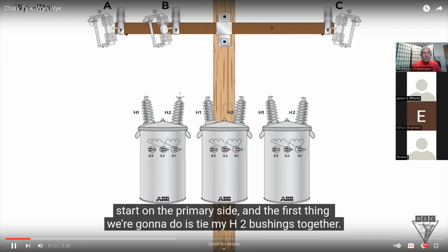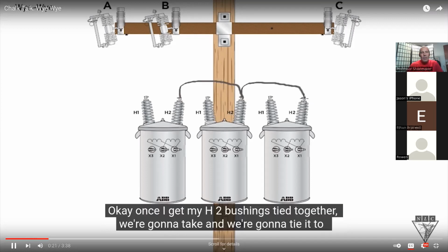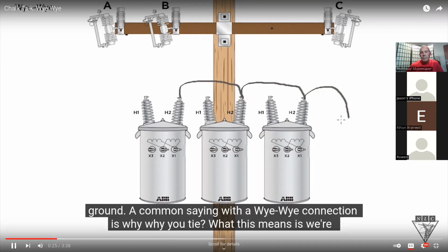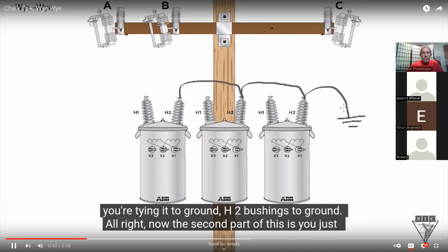I want to tie my H2 bushings together. Once I get my H2 bushings tied together, we're going to tie it to ground. A common saying with a YY connection is YY you tie. What this means is we're taking all the H2 bushings and tying them together, but that tie goes to ground. YY you tie, you're tying the H2 bushings to ground.